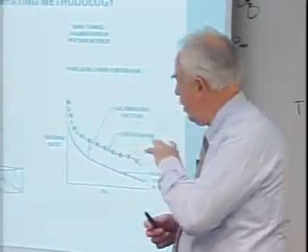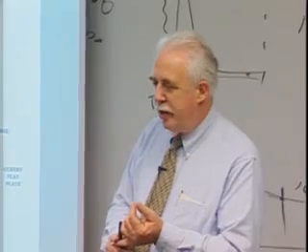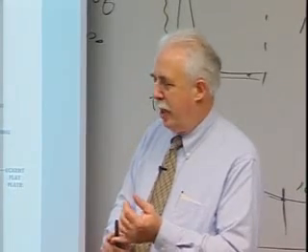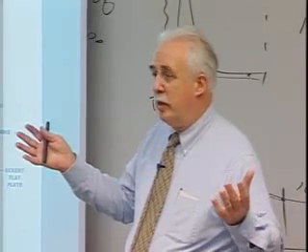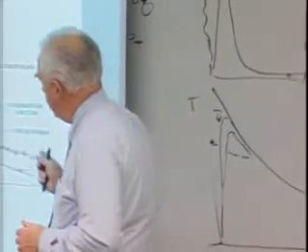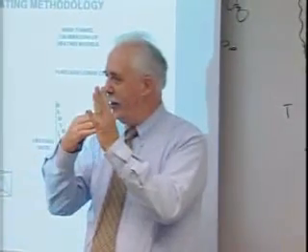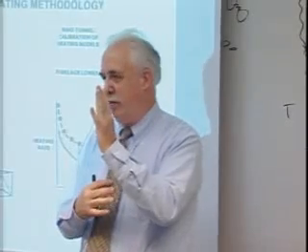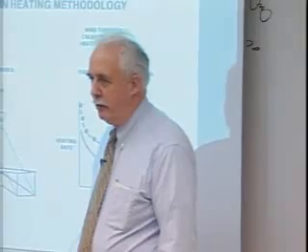All right. I mentioned 3 levels of aerothermodynamic methodology. One is to correlate in the wind tunnel and relate everything to reference heating or stagnation point heating, which is what we did on the capsules, which are good blunt vehicles. The real technology challenge on the shuttle was the geometry. It's a lot more complicated than just a shock and a stagnation point and flow around a blunt vehicle. You name it, you've got it in terms of flow on this thing.